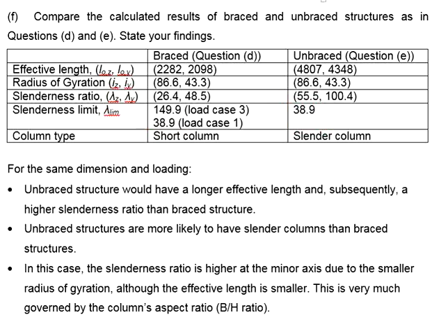Next finding. In this case, the slenderness ratio at the minor axis is normally higher than the major axis. This happens in both braced and unbraced structure. You see the minor axis having the bigger slenderness ratio. Same goes to the unbraced structures here. If you look into the calculation steps, although the major axis having the greater effective length, because of the rectangular shapes of the column,